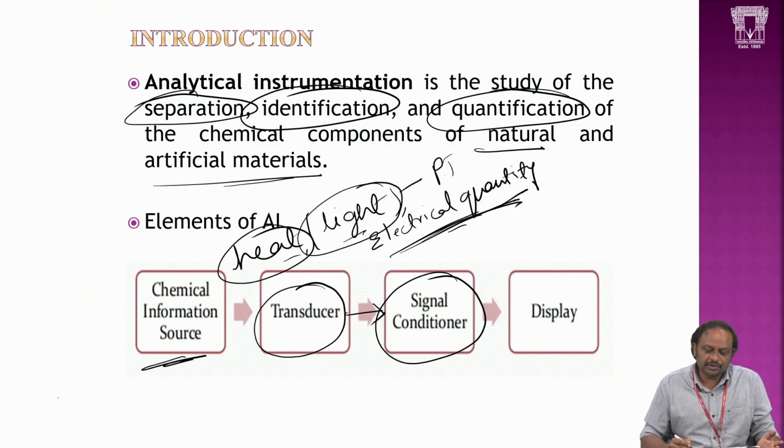So usually we signal condition it properly, by applying proper amplifiers, chopping down to the normal level, and using proper A to D converters. Any noise signal present in the environment is in analog form, so if the original signal is analog, it can easily be contaminated.